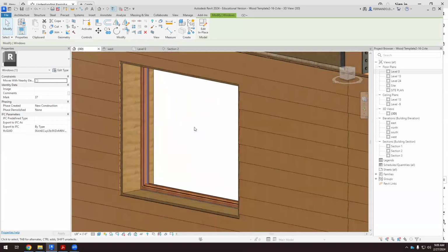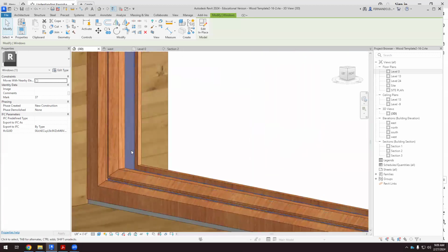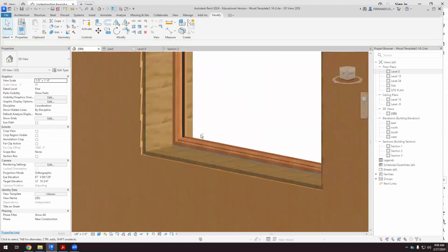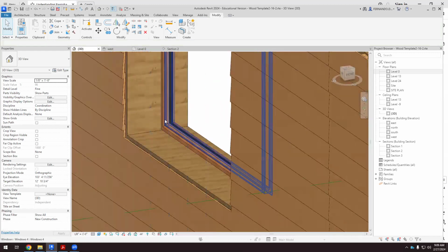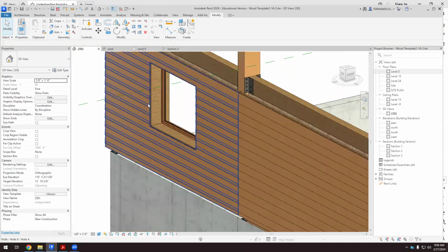around the frame so that when I'm placing the glass and I hit some of the frame, if it's a wooden frame, usually glass doesn't break when we hit the wood. But if we're working with aluminum, it's very easy, placing the glass on an aluminum frame, and when the glass is slightly broken, you have to replace that piece and it's very expensive. So that's why people are very careful, and we have this elastic element so that we don't break the glass. So we have something elastic around the frame, and now we can place the glass.